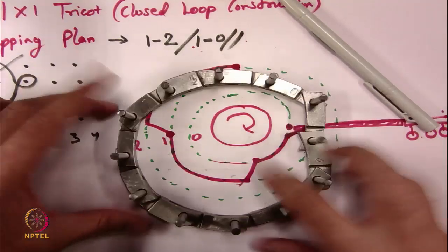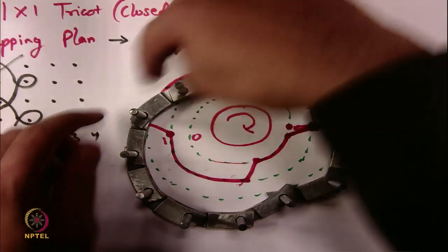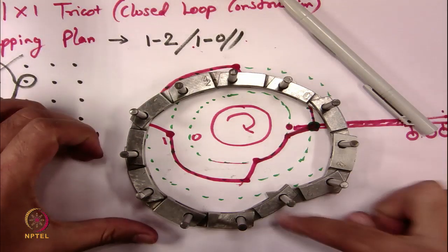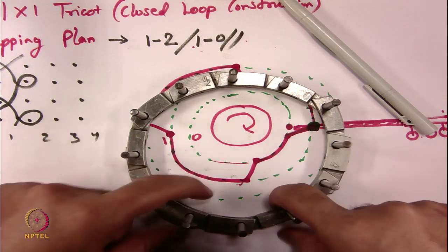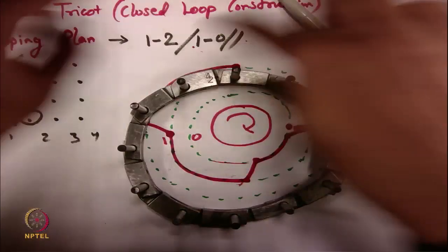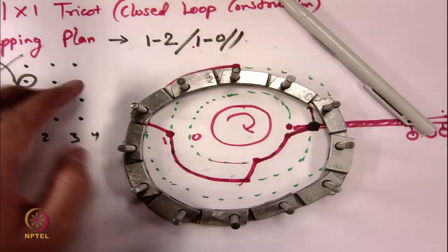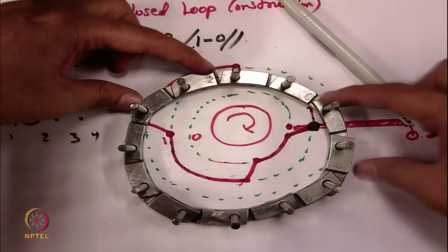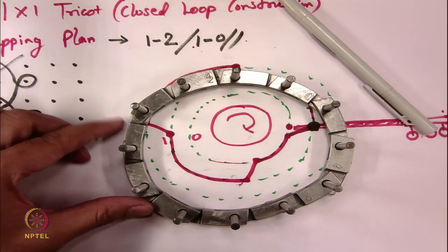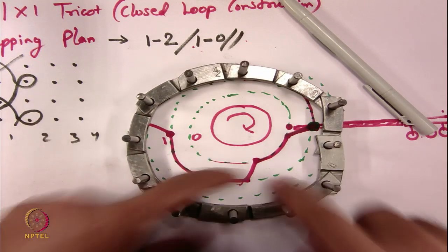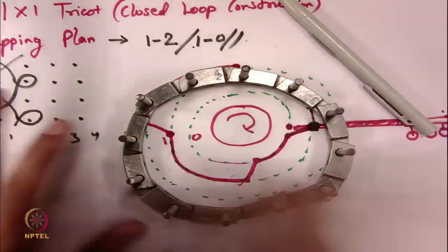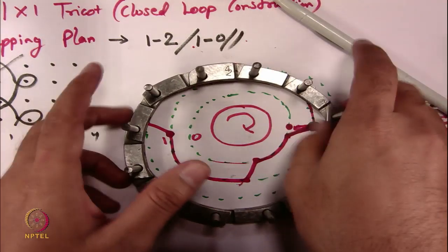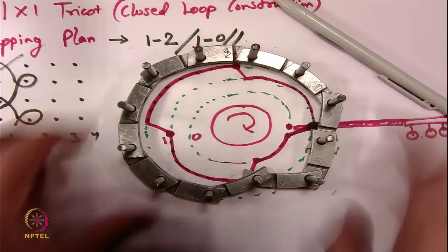So, now any time if you follow the sequence 1 2 1 0 will be coming. So, this is 1 2 1 0 1 2 1 0 1 2 1 0. If your drum is of this much radius, in one complete rotation it will be making 1 2 3 4 5 6 courses. So, depending on the radius of your pattern drum, you can keep following the sequence of these chain links and keep creating the courses. So, this is the simple one.